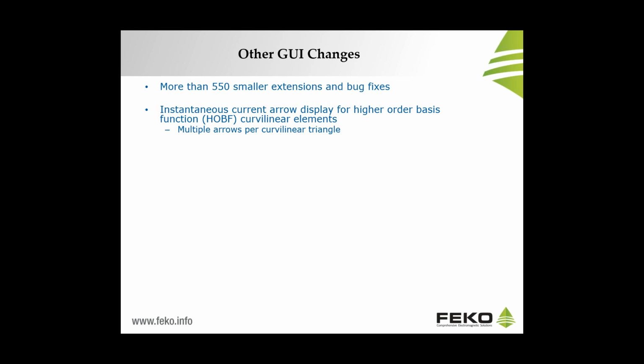And now if you want to display the instantaneous currents, you will be able to use multiple arrows per curvilinear triangle. Regarding options in FEKO for exporting, you will now be able to export information about the residuum for iterative solvers, and also information about the mesh to the out file.